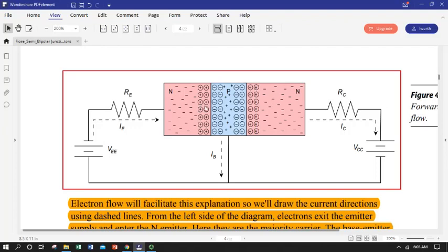Okay, so if this were a diode, having allowed those electrons to climb the energy hill across this interface, they'd hit the P material, and in a diode there'd be a lot of charge carriers in the P, a lot of holes pre-existing here. And those electrons would combine with the holes and complete the circuit, and we would effectively have positive charge flowing into the P, which is represented by electron flow coming out with a base current. But that's not what happens in a bipolar junction transistor.